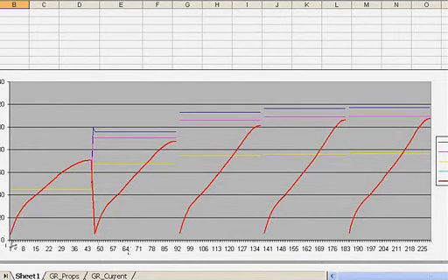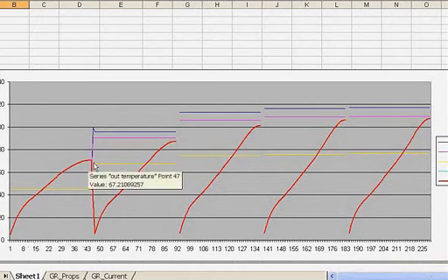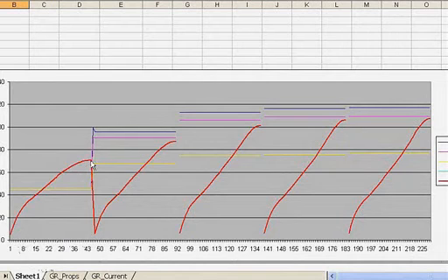So I'm modeling a quarter of a cycle, which is 25 microseconds in a 10 kilohertz sine wave, and then coupling the results to the transient magnetic, which might be in hundreds of seconds, on the basis that all those quarter cycles are the same, so I only need to do one. And then I do the quarter cycle as it gets hotter. But you can see the magnetic, the red trace, is starting to get nonlinear.